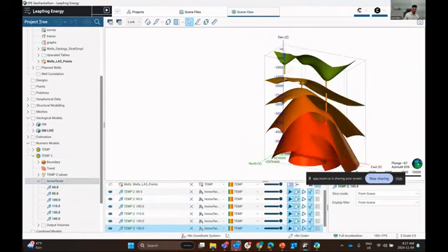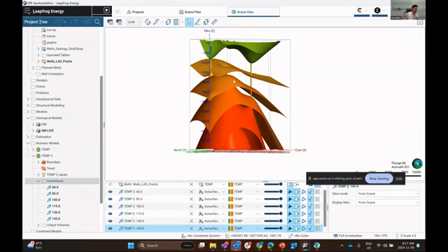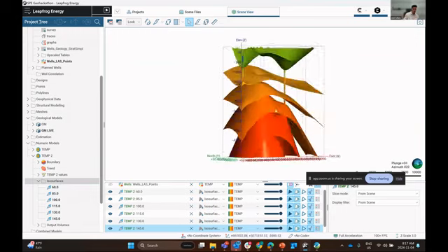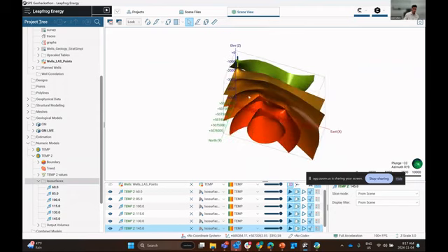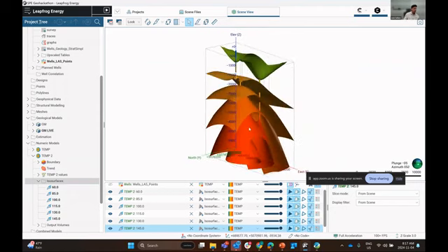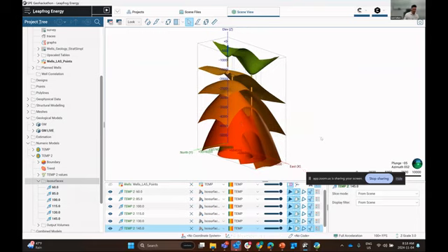And we can drag and drop those in. And now we have a much wider breadth of the temperature ranges associated with the values that we used to interpolate between these drill hole objects. Again, this is an RBF interpolant, but you will have access to multi-domain RBF interpolants and also linear geostatistics, which again, we won't have time to cover today.